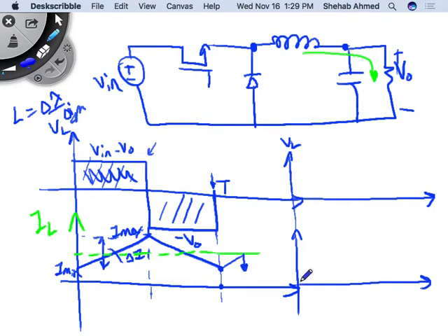current in this case. Let's say it will start at 0, but I've dropped the average value considerably so that I'm crossing here, right? And this was my original waveform. Like this, let's say this was my original waveform. This was the original wave that I had here. The switching period is from here to here. Right? Now I changed that. I kept dropping the average value until the minimum value of inductor current reached below 0. Right? So there's no such thing as below 0 because it cannot go negative. Can the inductor current go negative?